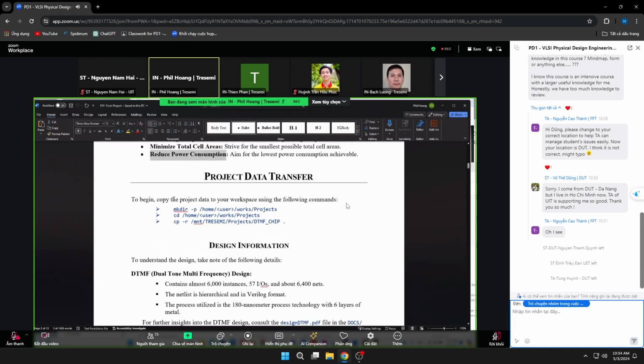So now, like I mentioned, you will copy over, you don't refer to the project at all. So you have a work area, you have your homework area, you create something, say final project or whatever. I suggest you just follow this format so we know where to look for your final result. Then you cd to this and you copy -R to copy everything under DTMF chip. So basically just the inputs and documentation, no scripts. The scripts are the things that you're going to create.